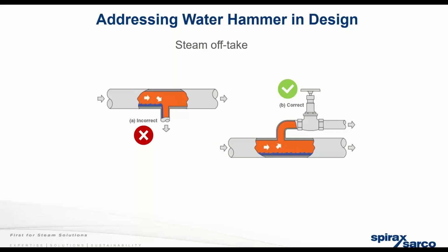Steam takeoffs, pretty basic. We want to take off from the top of pipe and not the bottom, as we'll send that water, potentially causing water hammer, to our equipment and our valves, our control valves, et cetera, et cetera, et cetera.